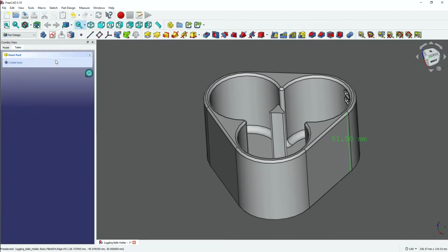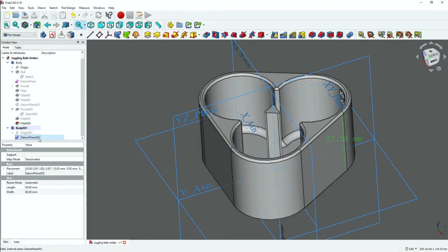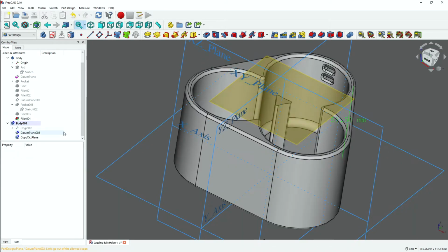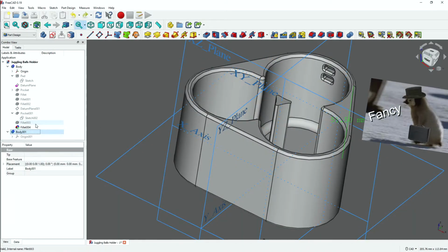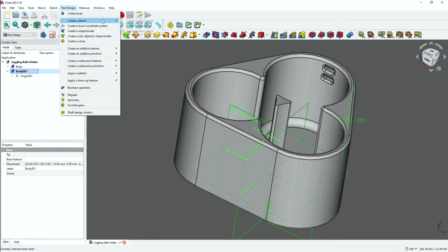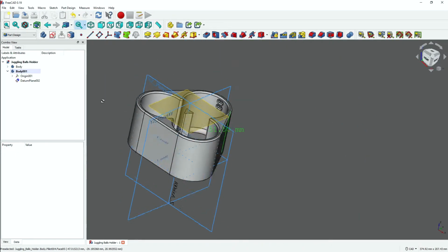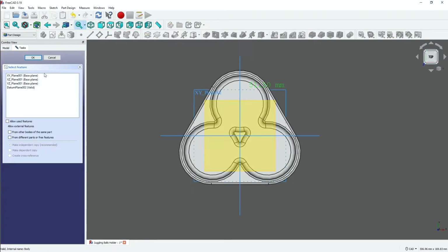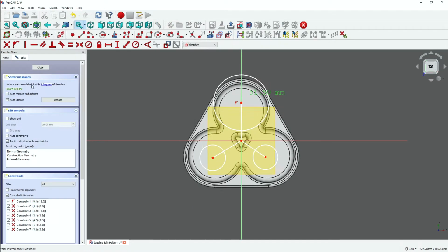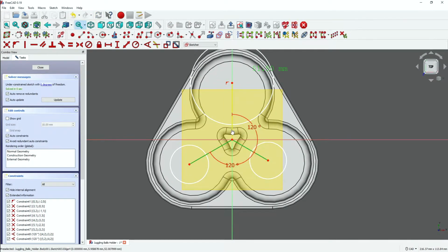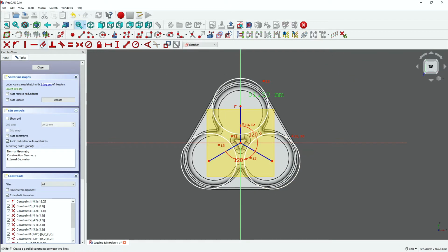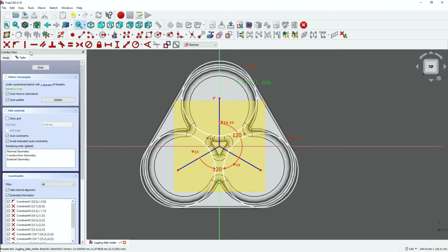Alright, and so now I'm actually going to, for the first time, make an assembly in FreeCAD. And to my surprise, there's no assembly files or assembly structure. There's no native assemblies in FreeCAD. You'd have to use a different workbench. That's an add-on. But there are a few options there. But I just designed it in place, which is another option. I don't like that option, but it's another one.